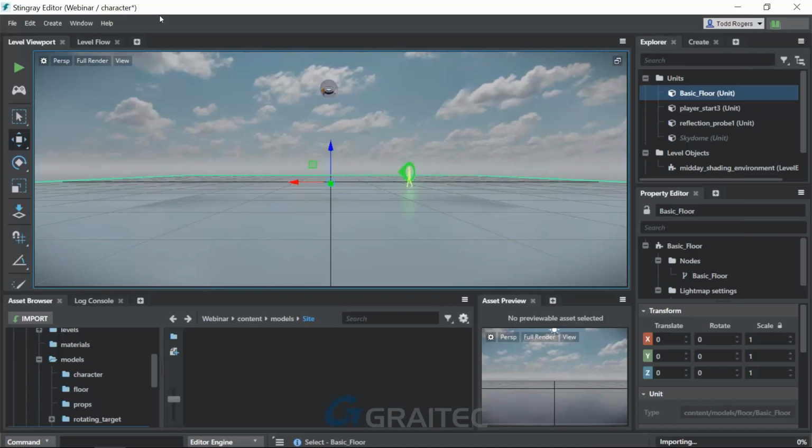Okay, so Crystal asks, what processor and how much memory am I running on my computer? I have 16 gig. The processor is an i7, I think it's 2.7 gigahertz. But the problem is I have an NVIDIA Quadro, which is geared more toward AutoCAD and its verticals. It is imperative, if you're going to use this type of software, to use something like an NVIDIA GTX.